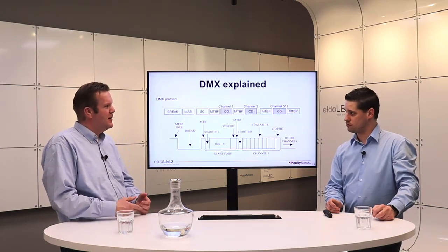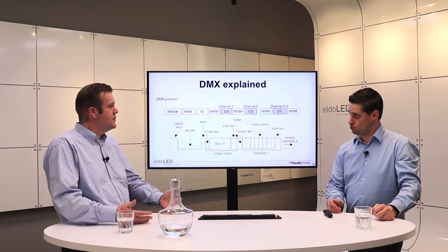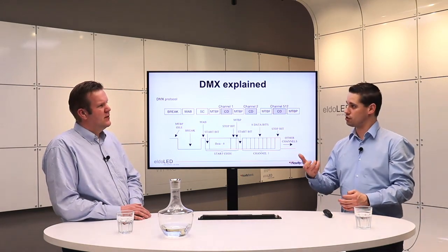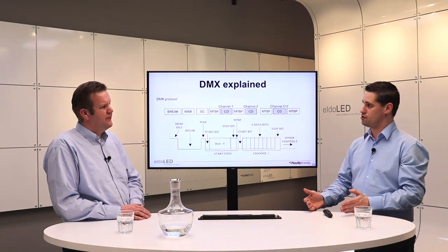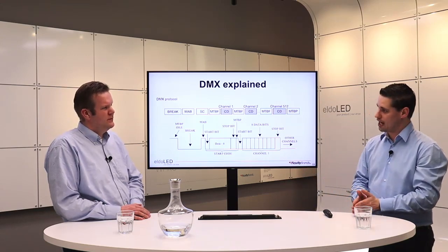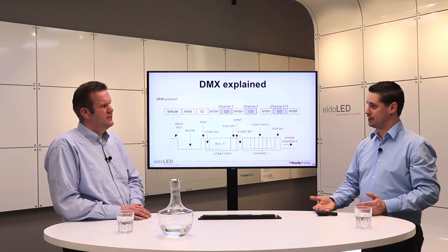And if you use 16-bit, all movements and dimming were much smoother. If you want to rotate 720 degrees, 250 steps are not enough to do that smoothly, and that's the reason why they allowed combining channels to have a higher resolution for the applications that required it.